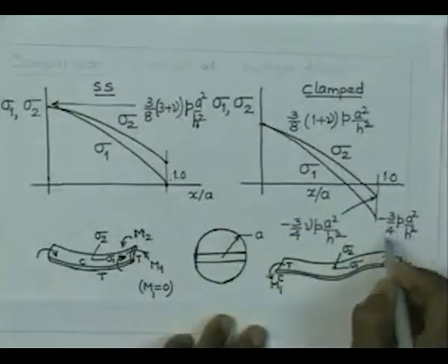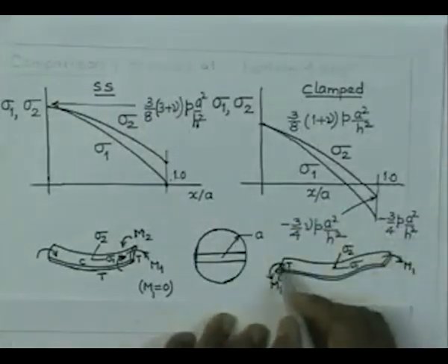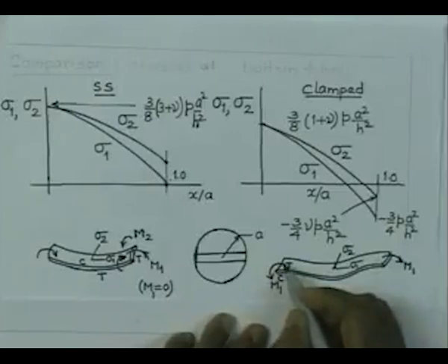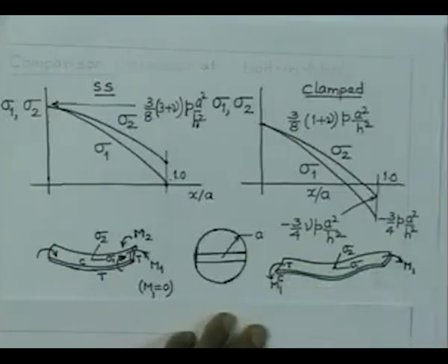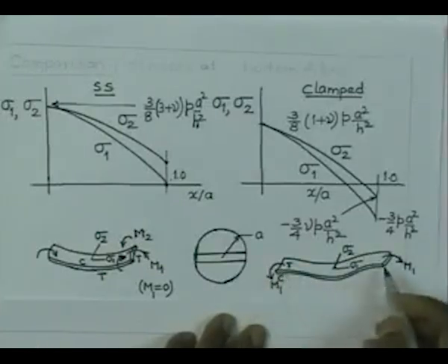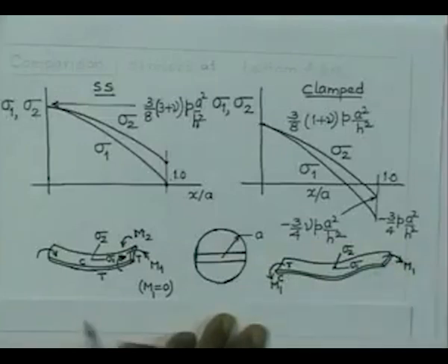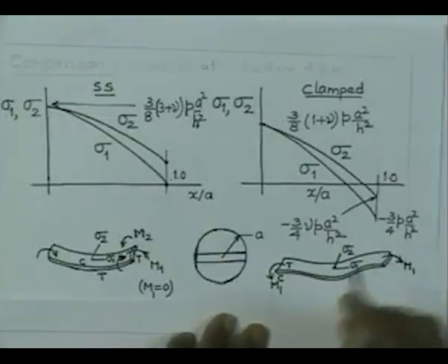And that is what is your sigma 1 stress is compressive here. Now, if this is the moment acting, the strip will try to have anticlastic curvature like this. So, it is going to be curving with the center of curvature at the top, and since this curvature cannot be permitted because it has got to be in contact with the support, this has got to be undone.